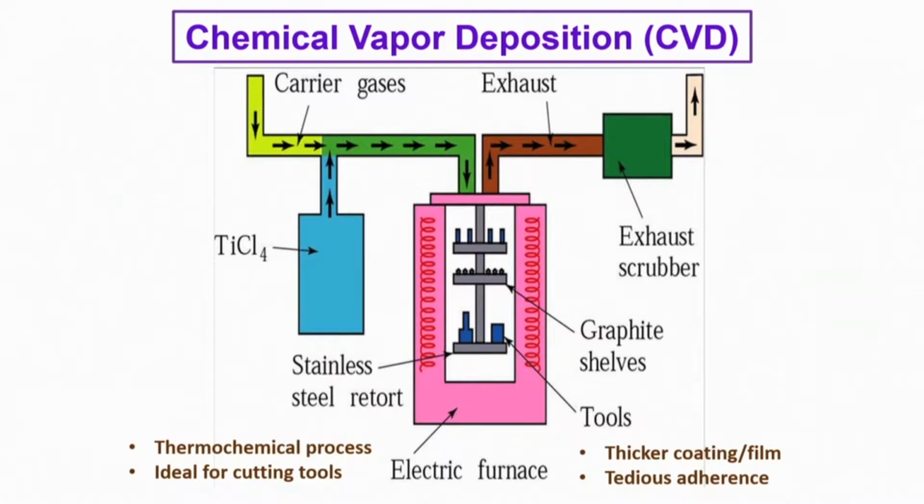Now, compared to PVD and sputtering, we are going to discuss chemical vapor deposition, CVD, which is essentially about the same technique. We are thinking about low thickness deposits, films, typically a few tens of micrometers or less. In the limit, we can create very thin layers, a few tens of nanometers, in alternate sequence.